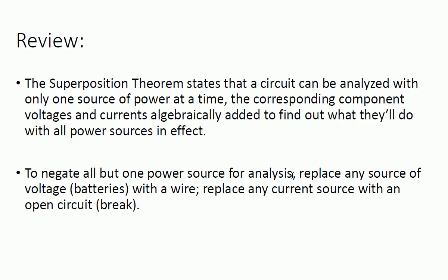Okay, right, review. The superposition theorem states that a circuit can be analyzed with only one source of power at a time. And that means we can use Ohm's law for this circuit, and then we do these calculations several times. If you've got 3 power supplies, 4 power supplies, or whatever, we have to do it 3 or 4 times and then create this big table and sum it all up. So either add or subtract, depending which way the current flows, or which way the voltage drops are.